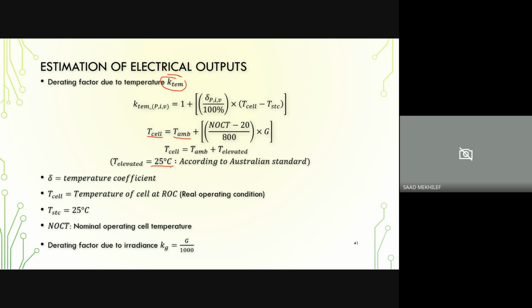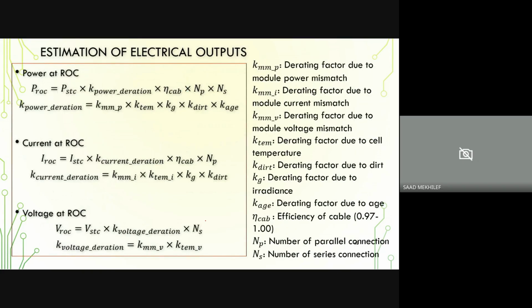And that's what reduces the efficiency of the cells, because like I said just now, the STC is at 25 degrees C. When you put it outside, it's a different environment condition. So that's why we call it derating. These are the estimations of the power at different temperatures.